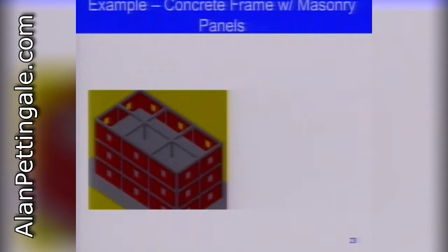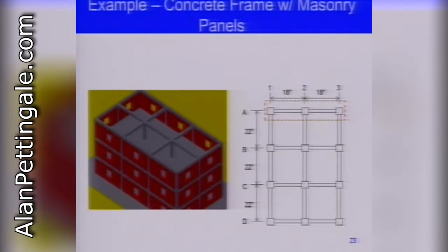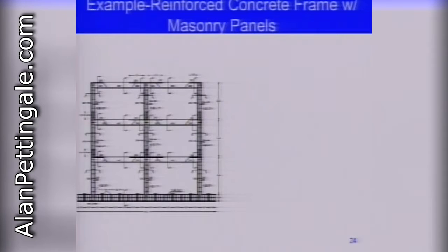Then that would be an infill frame, like the one I discussed before. You see that's a frame I designed based on the practice in California in the 1920s. And at that time, they never considered earthquakes, they never considered lateral loads.